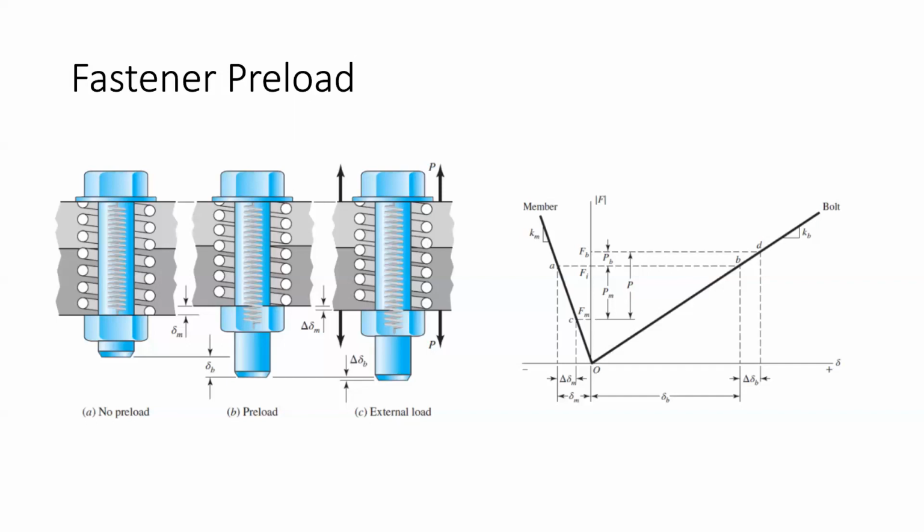So you can kind of model this as the amount of area that you have exposed. Like if you were to take a cross section of your thread and see where that cylinder cuts through the thread, that area is where you're loading it. So in practice, more often than not, this is done empirically, and there's a formula that you can use to determine the failure point of the thread.